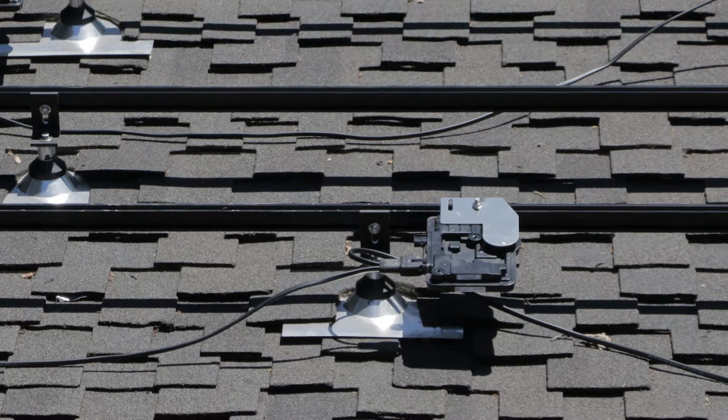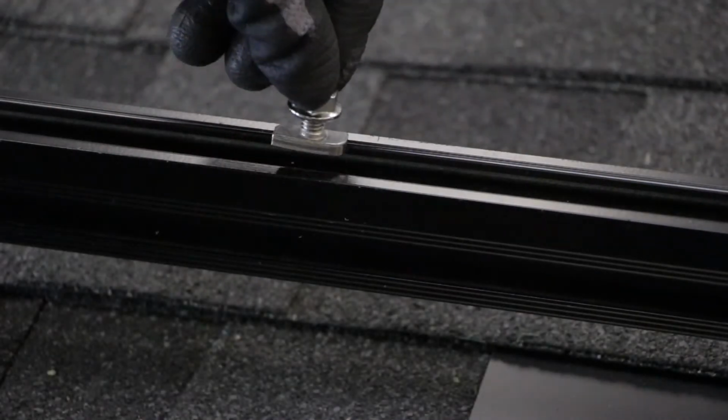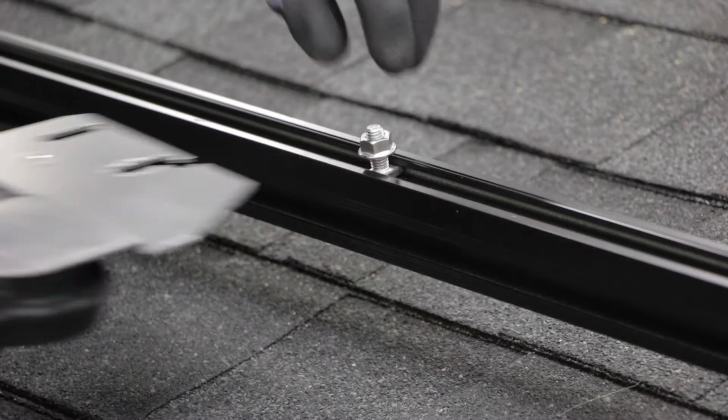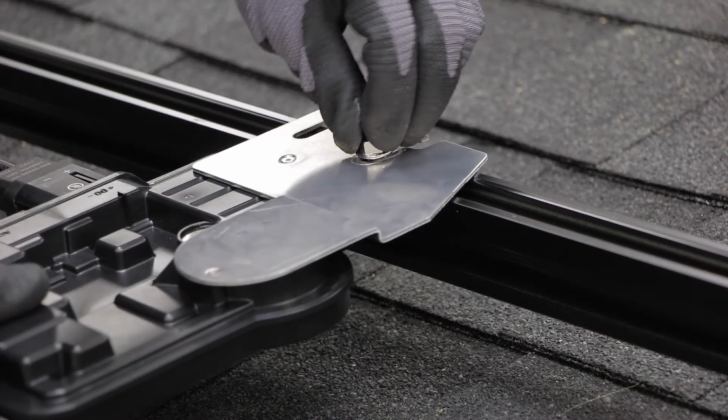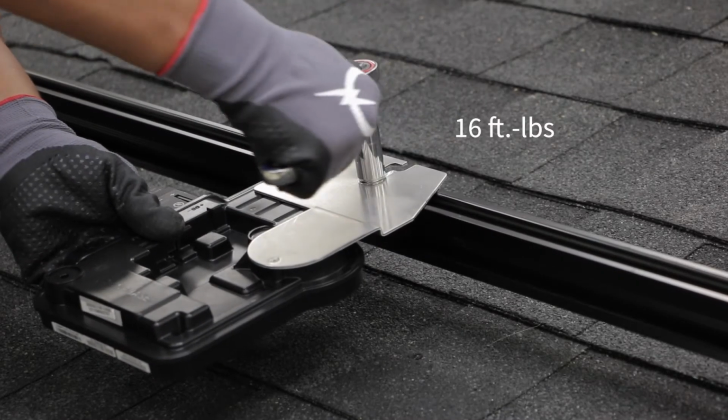Module-level electronics are typically attached to the rails and wired before the modules are installed. Optimizers and microinverters can be attached to the top of the rail using a standard QRail T-bolt. Tighten the bolt down to 16 foot-pounds.